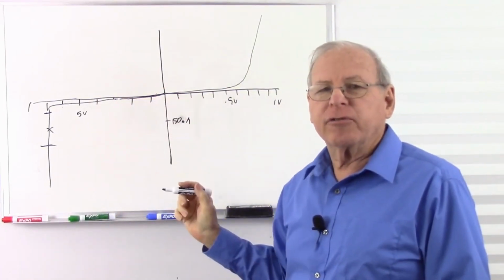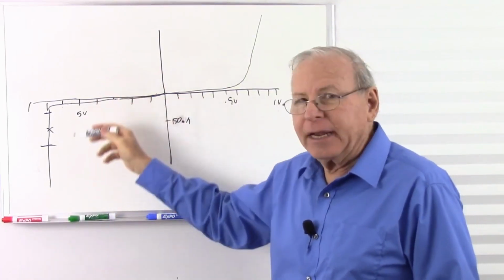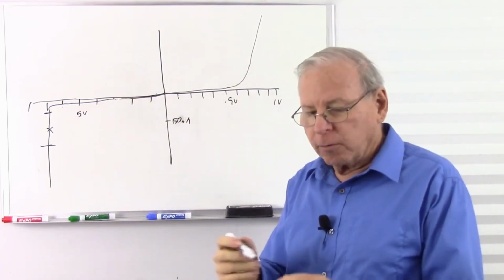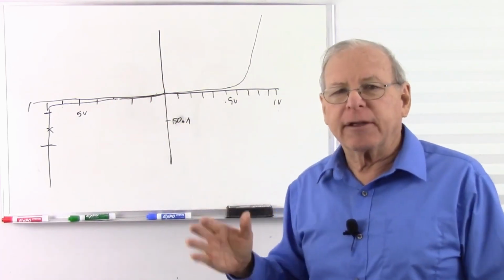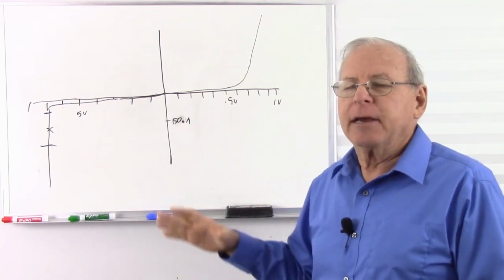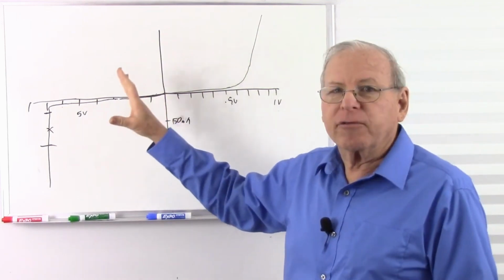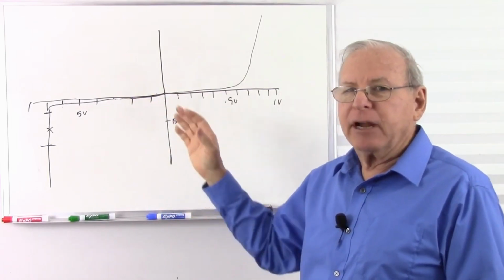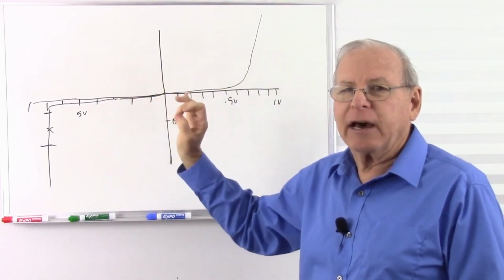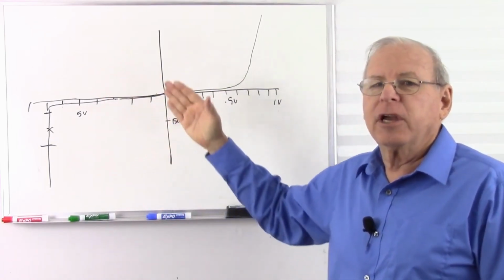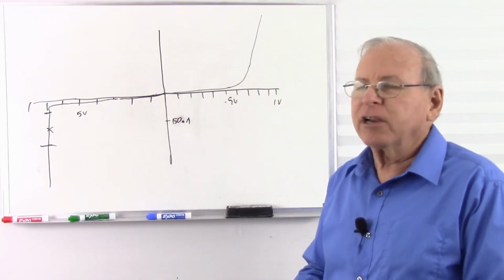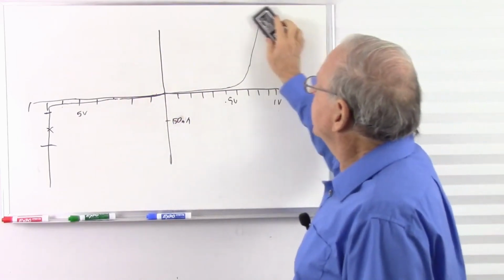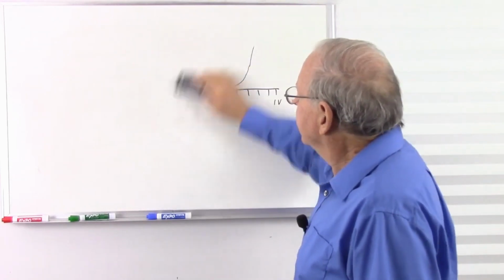We'll just choose a series resistor that keeps the diode within its power rating when it's operating normally. There might be some circuits we'll talk about another day where we have to be more careful about that, but typically we're not going to have to worry about the current changing through the diode that much. We're going to have small fluctuations, and the diode's there just to give us a steady reference in an area where voltages fluctuate. So in a nutshell, what is a Zener diode?